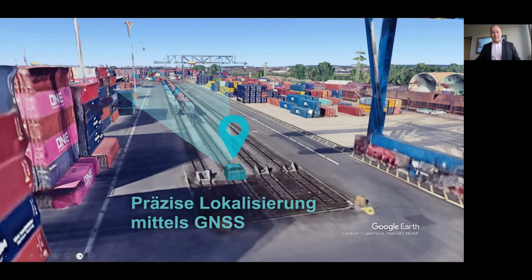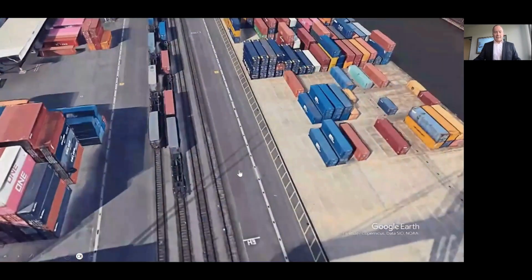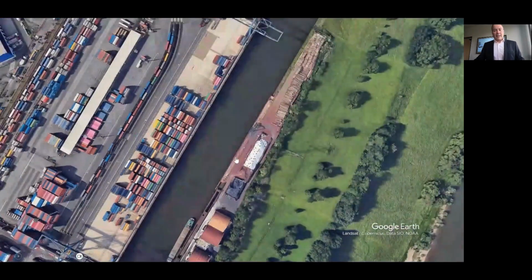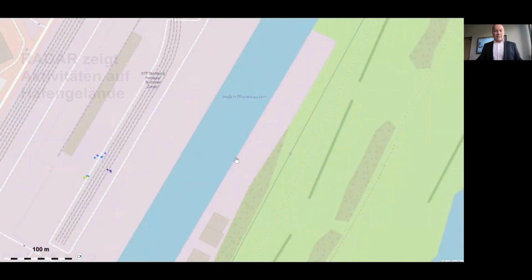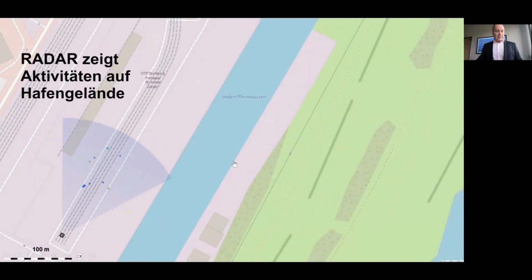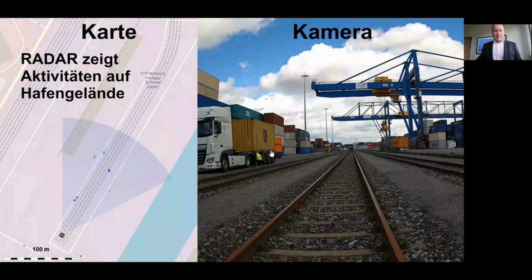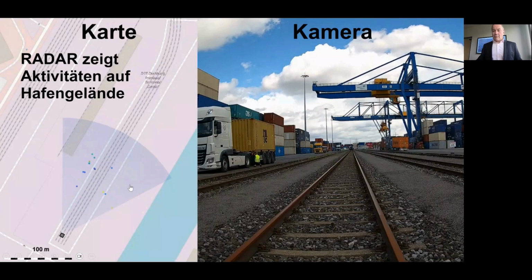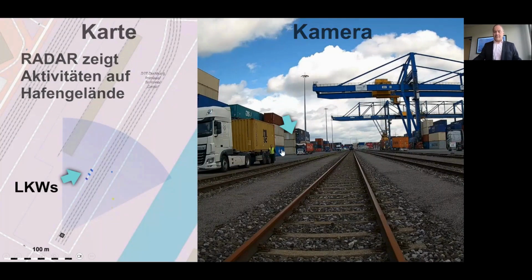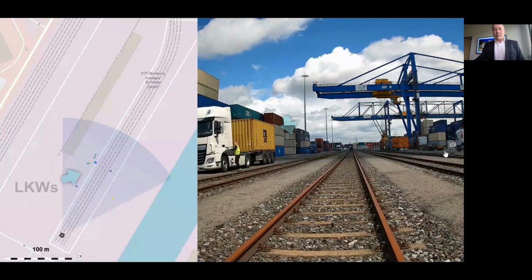And this shows you the scenario. So the train is coming, the end of the track is located by GPS, so we know exactly where the radar is located, and then we measure the reflections that we see from the environment. And you see there's lots of reflections to the left and to the right, and they are only caused by trucks driving along the tracks here.